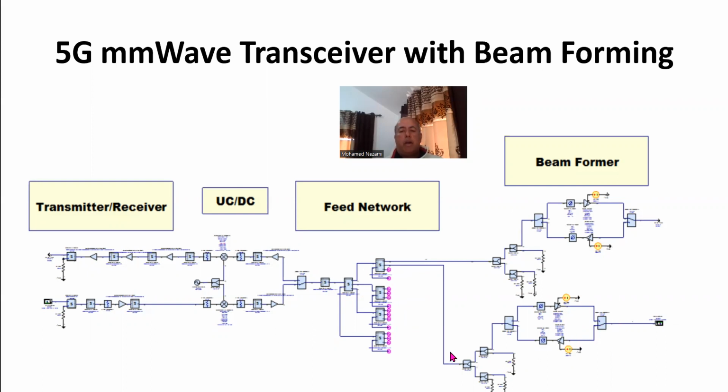So this is the receive path. Which I come in here, there's 16 of them that come in all the way here, 16 that come in here, get summed in here, filtered in here, and then get routed into this receive path, get down converted, and go all the way to the ADC. Likewise, on the other side, we have a DAC that plays the waveform at 3.5, it's converted to 27.5 in here, goes through a transmit switch, and then gets split 16 ways, because you have to provide the signal to 16 beamformer chips.